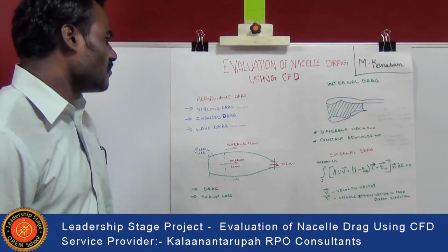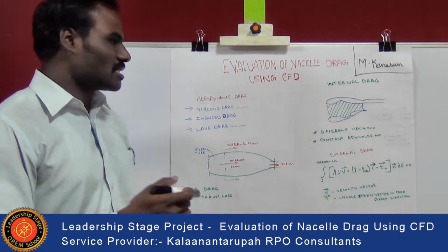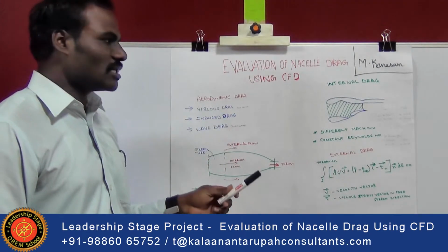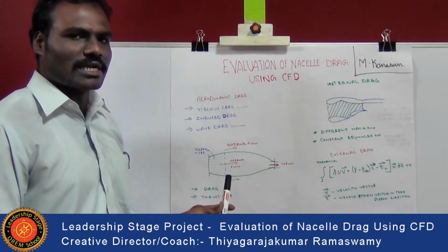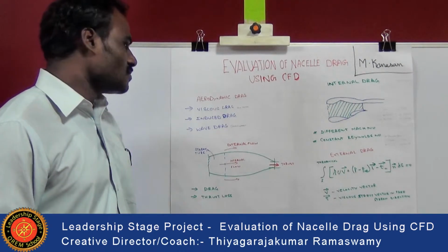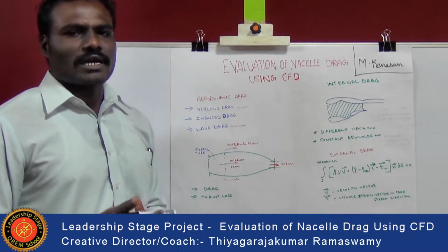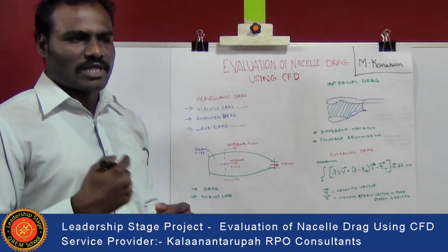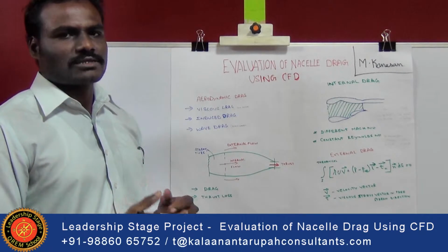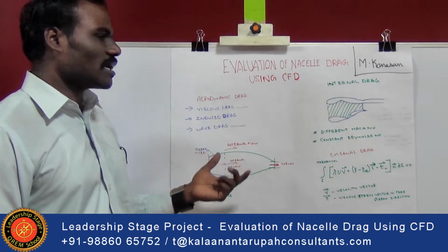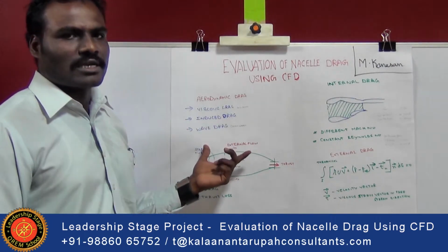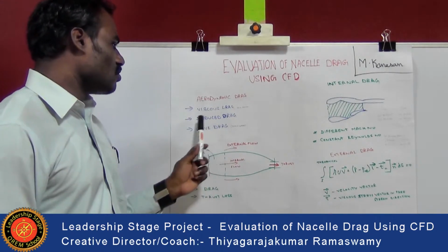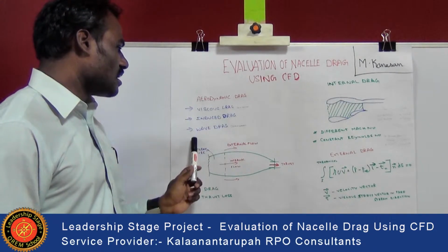Before entering into it, we just discuss what the aerodynamic drags are in this project, with respect to the internal as well as the external drag. The performance of the aircraft is based on the drag as well as the lift. Here we are going to discuss the main feature, drag, which affects the performance. The aerodynamic drag is classified into viscous drag, induced drag and wave drag.